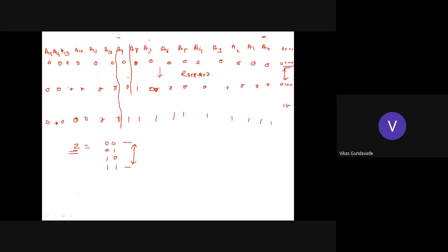So similarly, if we have 10 lines, how much address space will get reserved? First, the 10 lines are 0000000000. From here, the address will become 00, then this bit will become 1, then 10, then 11, and so on, up to how much space? Up to where all the lines become 1111.